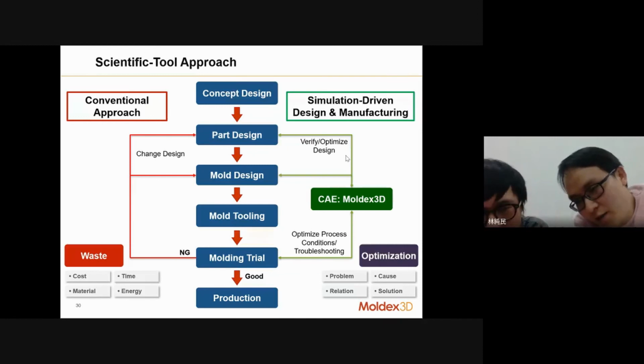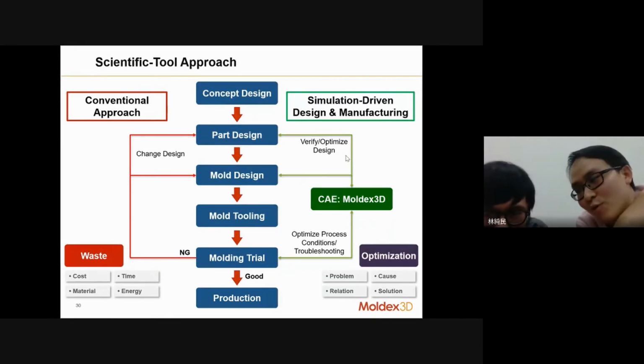You check whether the design now is able to be manufactured or not, or it can be manufactured but you will face many problems, so you need to revise it. So yes, we can help, but in injection molding we don't talk much about the volume. It's more about how your thickness is and what features you have, maybe ribs or not. Usually we don't, but we can help to verify your CAD design, your part design, just like illustrated on this page.